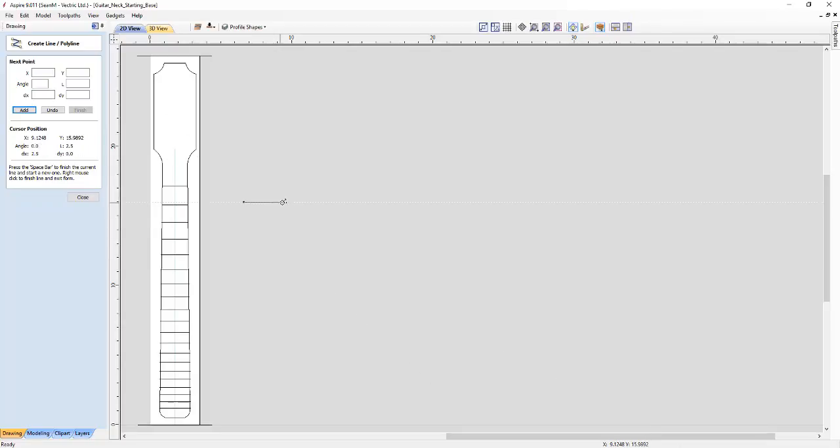Start to draw out the actual span itself, and you can see that the software will automatically give us a guideline to trace along. But as long as we've started to go in a particular direction, all we need to do is actually type out the length that we need. So if I type 18.5, you'll see in the bottom right hand corner we'll see value 18.5. Once that reads that, just hit enter, and that will create our first span.